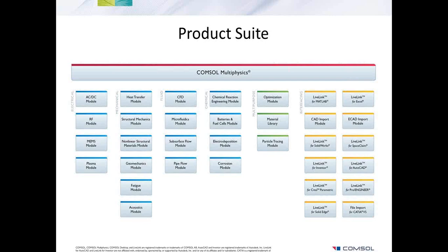At this point of time, what I'm thinking is that basically this would be an extension of the piezoelectric simulation, just like I mentioned a few examples where you can combine the piezoelectric effect with another physics. Essentially, this is going to be something like that. So you'd probably have to combine the piezoelectric effect with a full wave electromagnetic analysis. That would help you in modeling the optics part of it, and then the combination with the piezoelectric effect will help you to couple these two phenomena and see how you'd like to use the piezoelectric material to tune the optical effects that you're interested in. That would be the general approach.